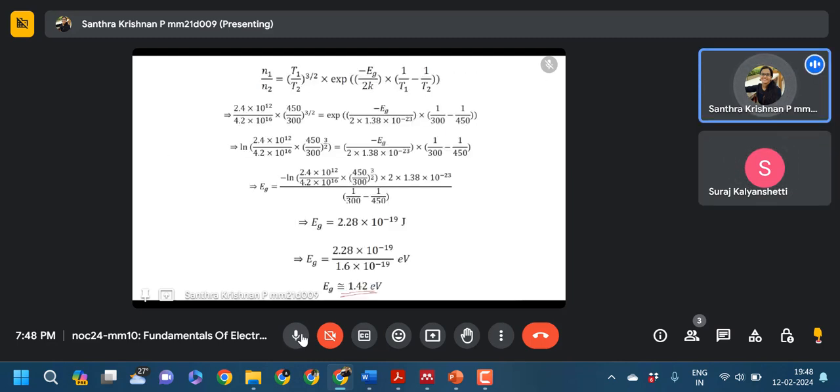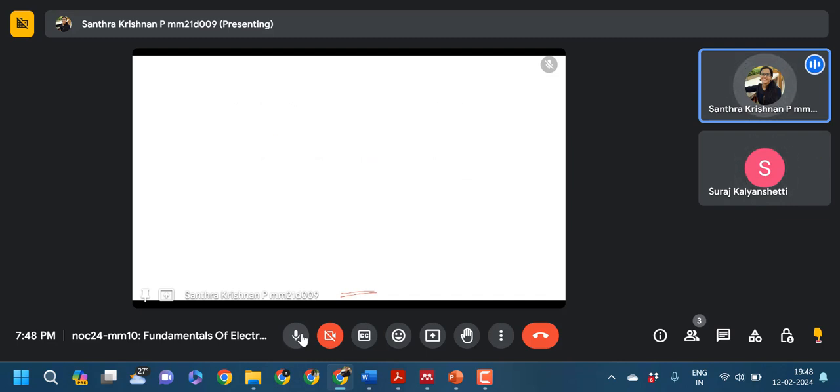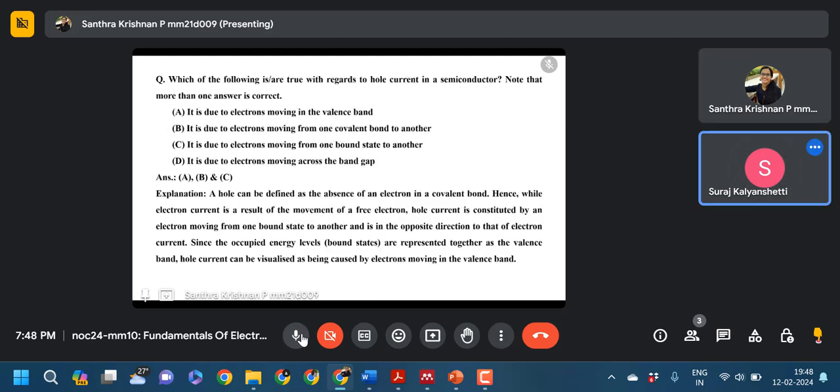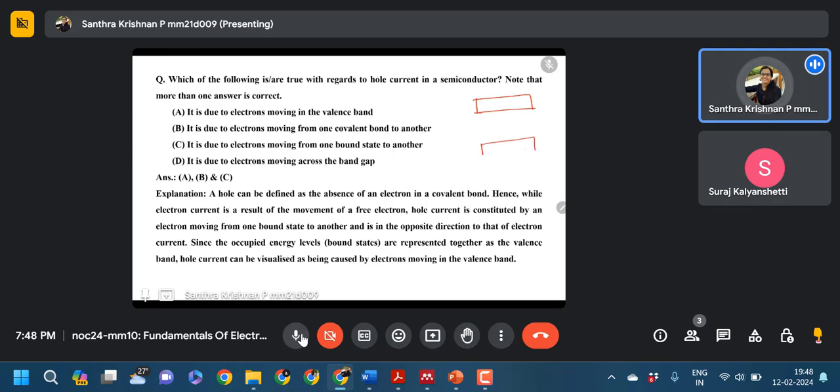Before we move on to that, about the other question: now when I think of it, I feel that option A is correct as well. I'll tell you why. Just go back. Basically, you have the conduction band here, you have the valence band here, right? You have all these electrons, and this is like nothing was there. And once a few of these electrons move up, in the valence band we are left with a few holes, and there are electrons as well, right?